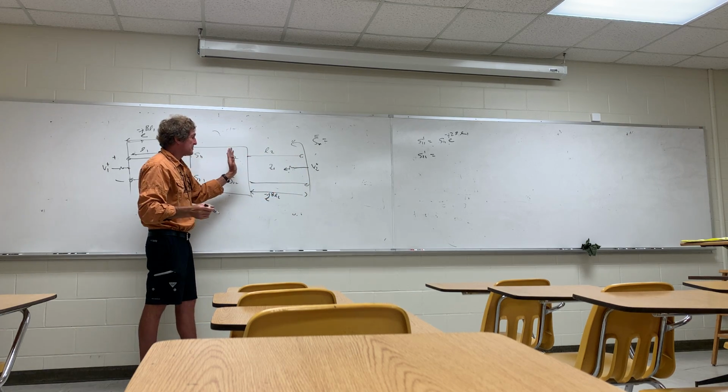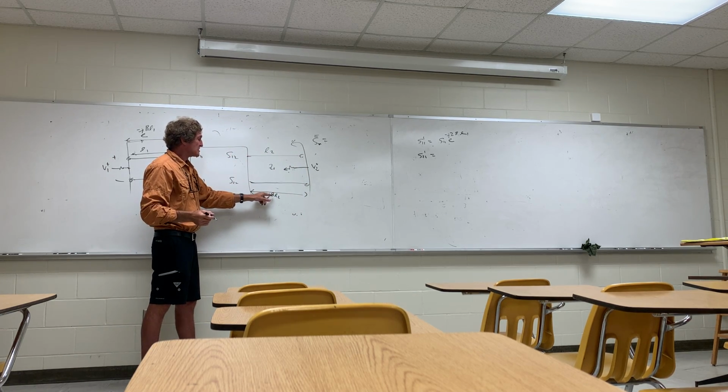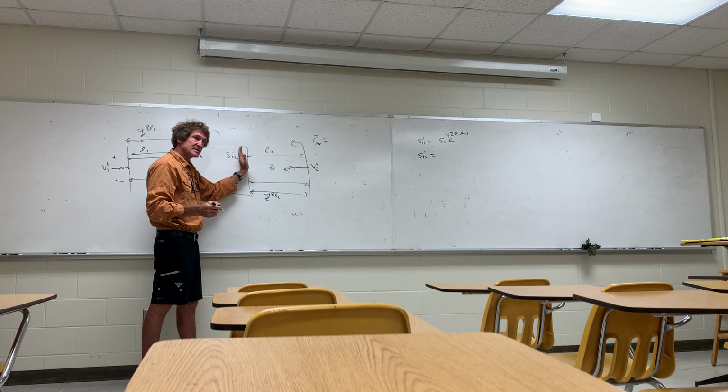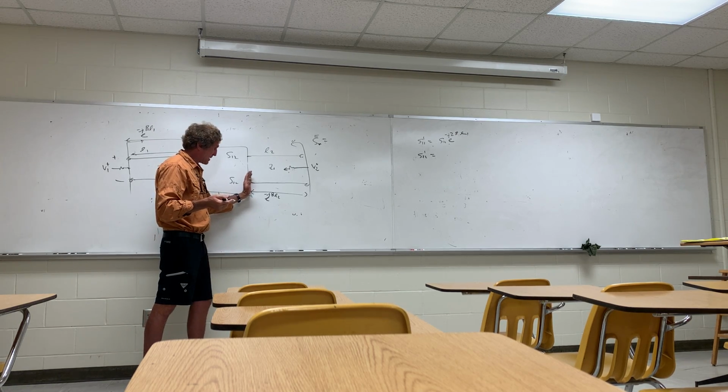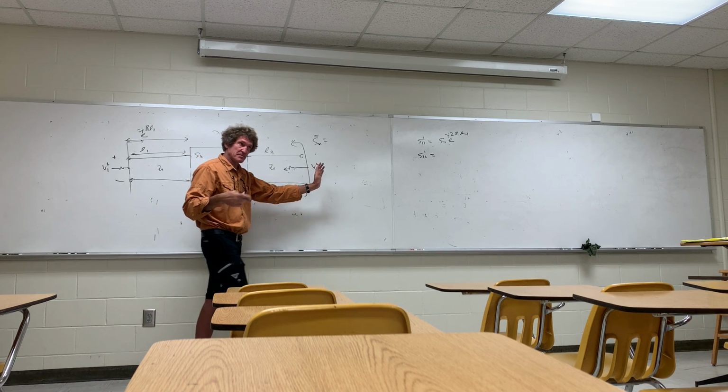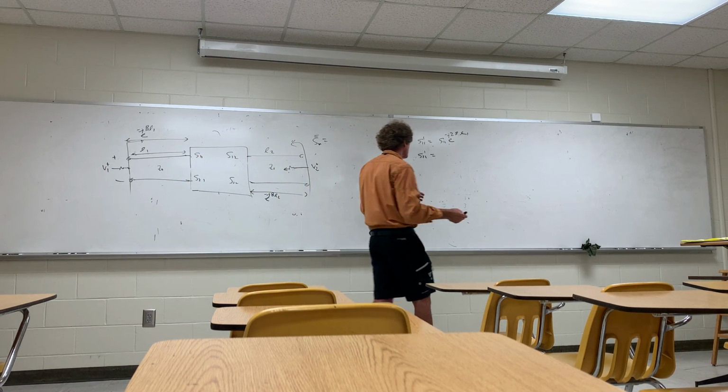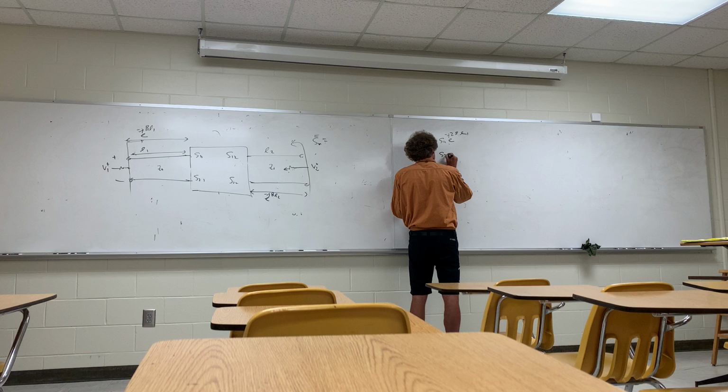It comes in, it gets a phase change of e to the minus j beta L2. It hits, right? Then it's V2 plus times S22, right? Comes back up, a second phase, just add this the same as the first, and I get simply the S22 parameter times e to the minus j 2 beta L2.